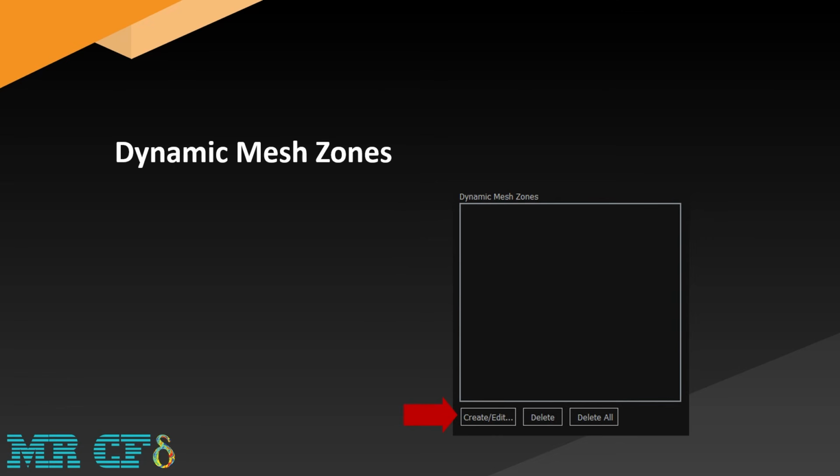Finally, it is time to introduce the dynamic mesh zone section. In this part, we have to determine the movement or deformation of the dynamic area inside the model. In fact, in the setting of this section, we specify the type of behavior or the type of movement for different areas of the computational domain.